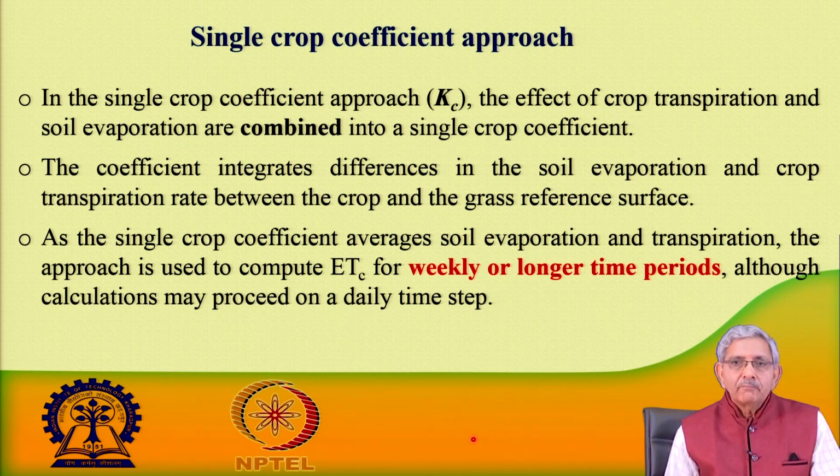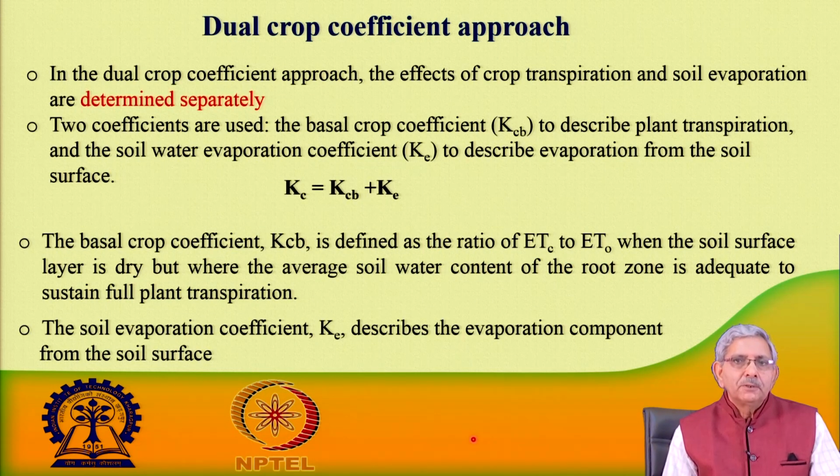So, here we are computing the evapotranspiration by taking a number of days. Particularly for surface irrigation systems, or to a certain extent on a weekly basis for sprinkler irrigation systems, the single crop coefficient approach is being used.